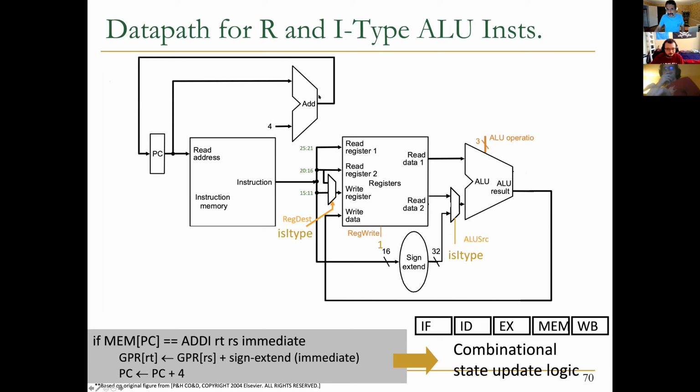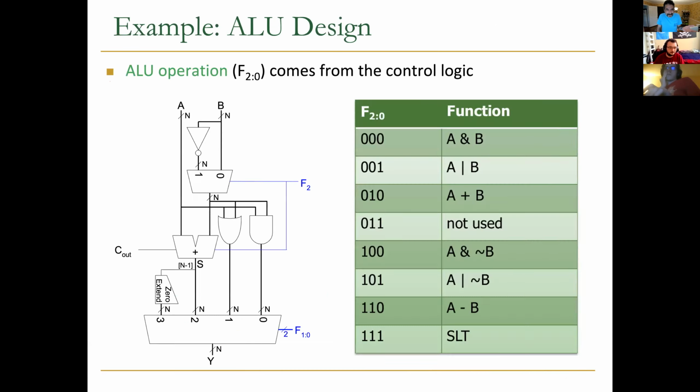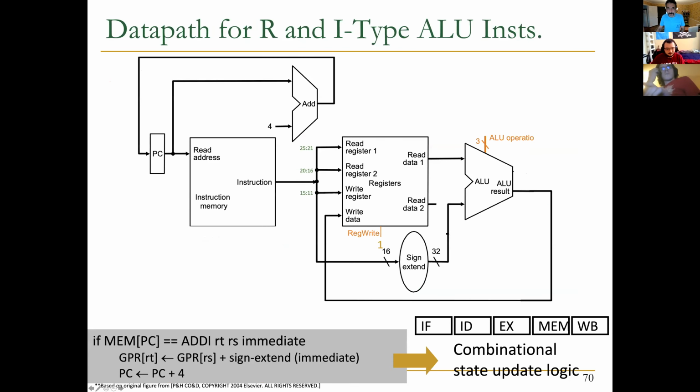We have one adder here, and part of the ALU implements add also, right? So you have an adder essentially here as well. So you could give it PC here, and 4. So you could remove these. One possible way is to get rid of this. You could wire this here, and then 4 here. Obviously, you need an element here, a mux, now selecting between 3, this one, and 4, depending on where the input comes from, and send the right signal.